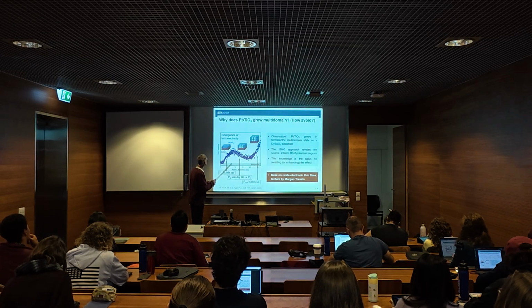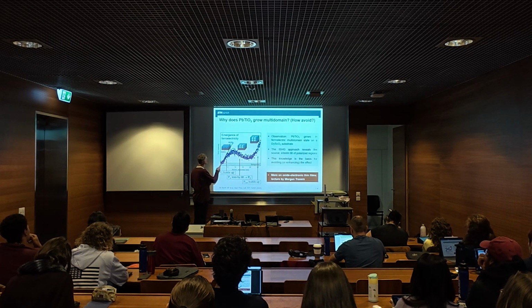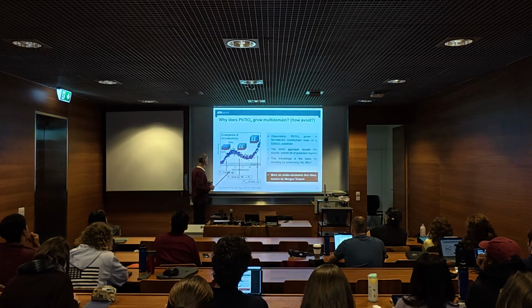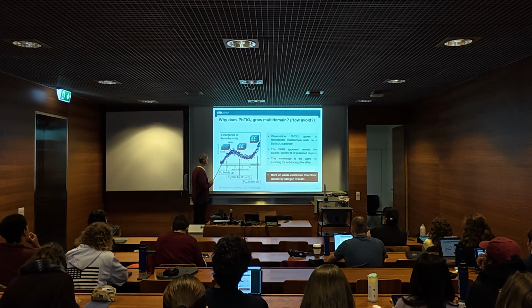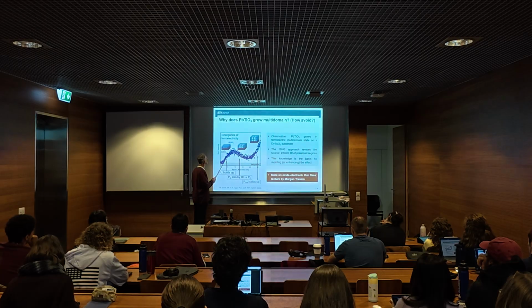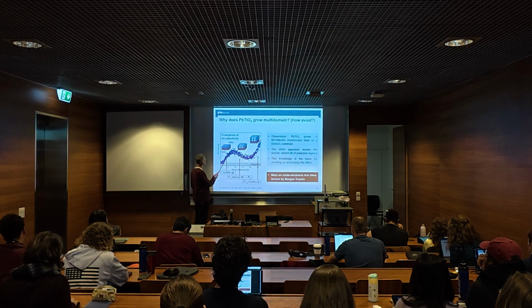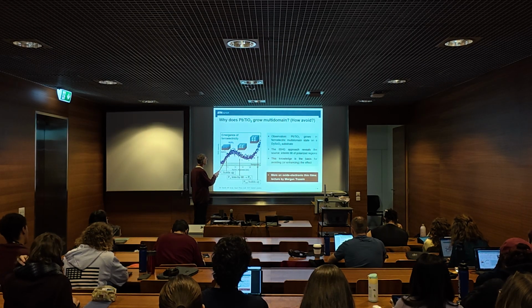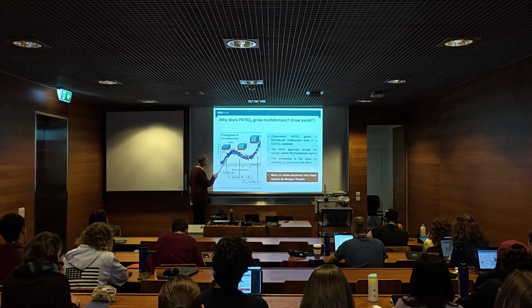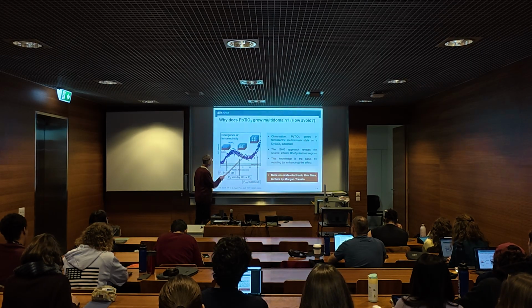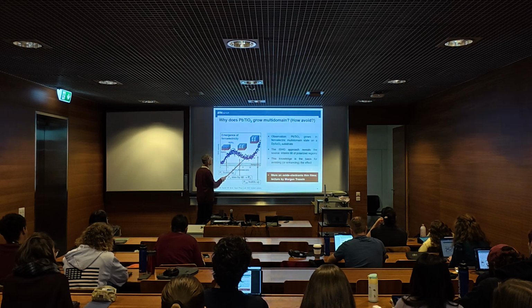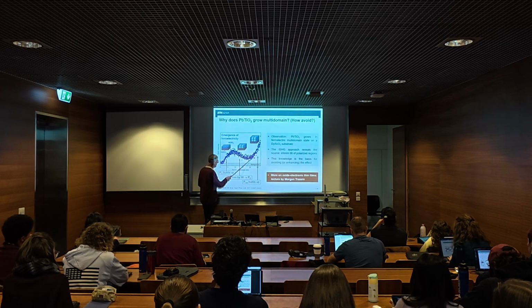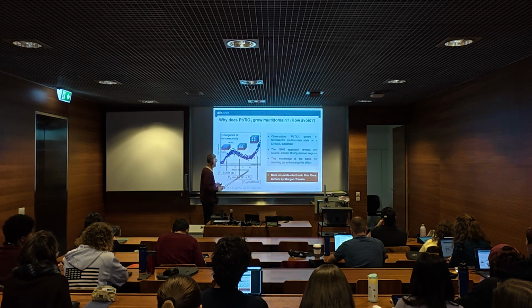So for example, here you grow a lead titanate ferroelectric film, and then you see what I've just shown. So it gets ferroelectric, the film gets thicker, so you get more of this ferroelectric frequency double signal. But then at some point, for a certain thickness, your signal goes down again. So the frequency double signal goes down. So somehow polarization is disappearing. Until then, from 20 nanometers, it's increasing again.